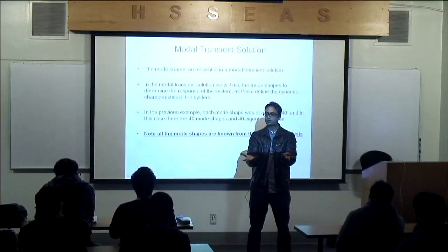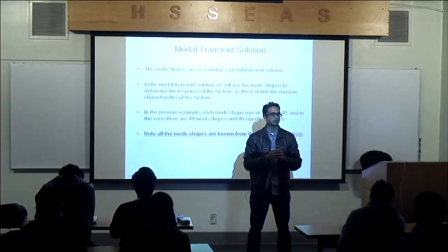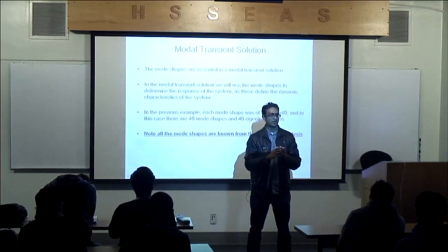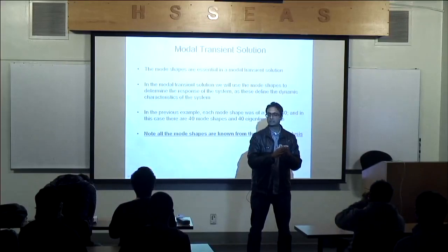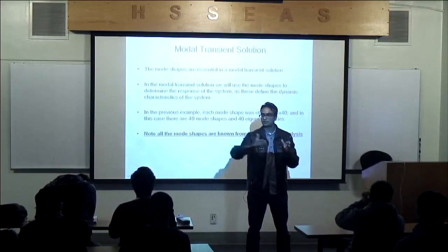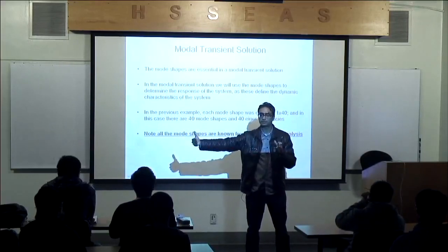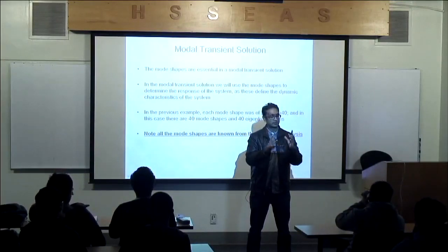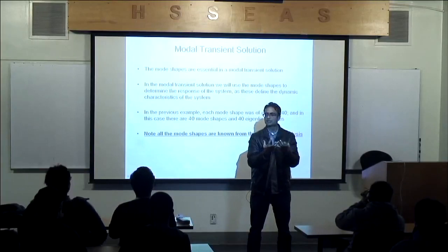That 40 by 40 matrix, my mode shape matrix, contains up to the information that's relevant for that structure, for that discretization, right? Because in reality, it's not all, because all would mean I need a matrix that's infinite, because there are infinite mode shapes. But because I've discretized the domain, this matrix now contains that DNA we're talking about, that dynamic information of the structure.